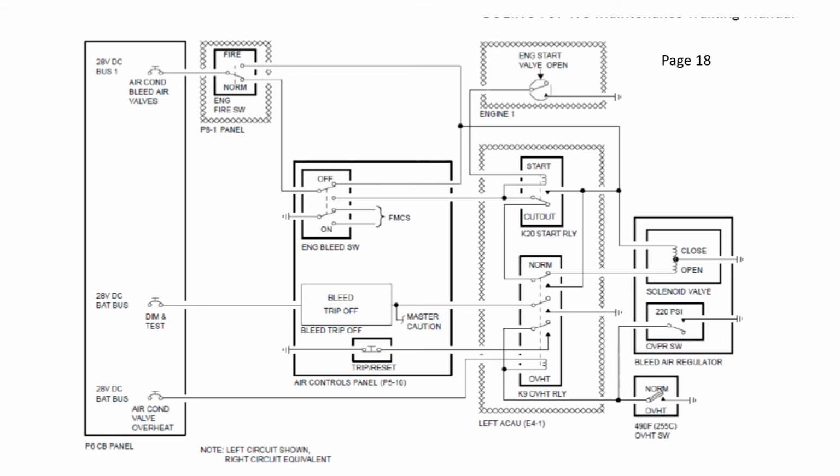Now just going back to the K9 overheat relay, we need to look at the lower set of the 3 contacts, because they have energized. When those lower set of contacts energize, the power supply that's come from the lower circuit breaker through the coil of the overheat relay is currently energized because of the ground signal provided by the overheat switch.